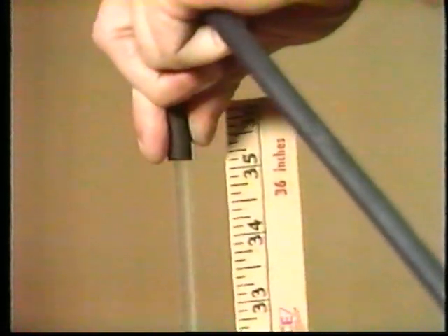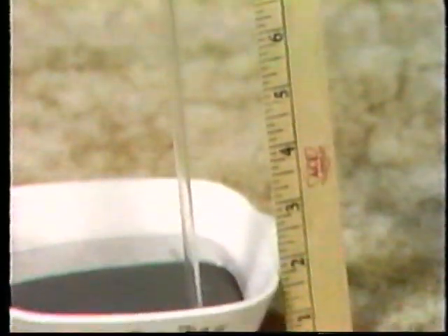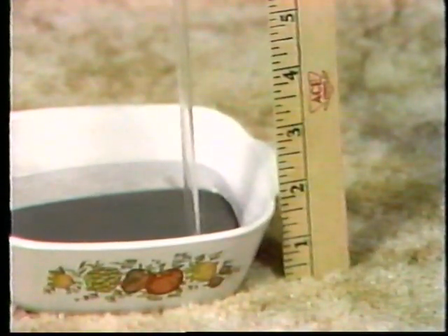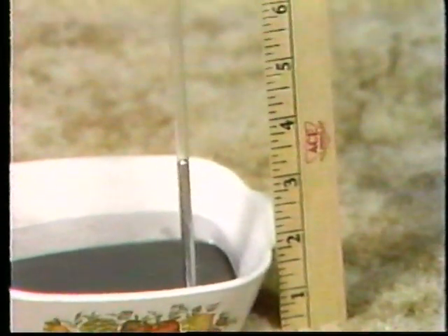Okay, now with a vacuum pump, we start to pump some of the air out of the top of the tube, which creates a partial vacuum. In this case, 10 inches of mercury. Now, since atmospheric pressure is approximately 30 inches of mercury absolute, and we now have 10 inches less here in the top of the tube, the atmospheric pressure pushes the mercury up the tube 10 inches.